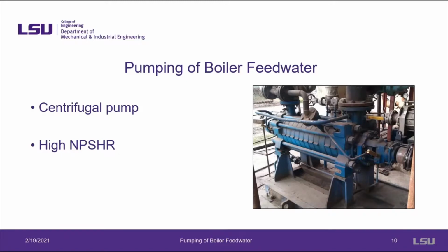Boiler feedwater pumps have a high net positive suction head requirement. This is due to the water's high temperature leaving the deaerator. For this reason, deaerators are placed high above the boiler feedwater pump in order to provide some extra head on the suction side of the pump.